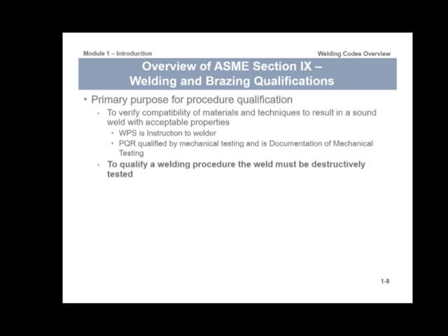But bottom line is a PQR is going to be destructively tested, and it's going to be documentation of the mechanical properties during that destructive testing.